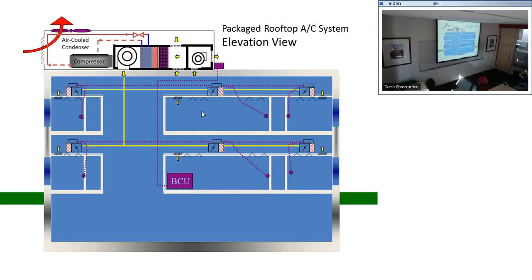No, first you're controlling how much air you're dumping in there, and then if you're down at the minimum, then you start reheating the air. So it's going to cool, and if the room is getting too cold, you're decreasing the amount of cold air going in there, and when you reach a minimum, then the reheat coil starts kicking on and starts warming the air. And that's how you're controlling temperature.